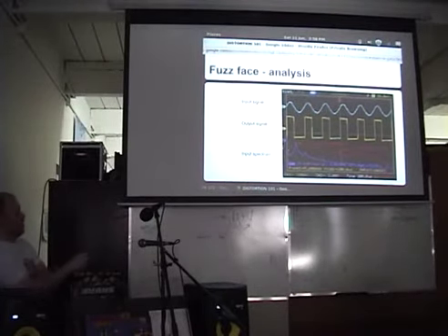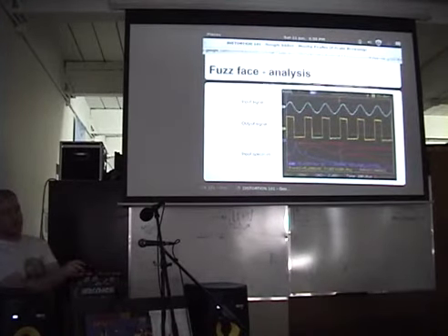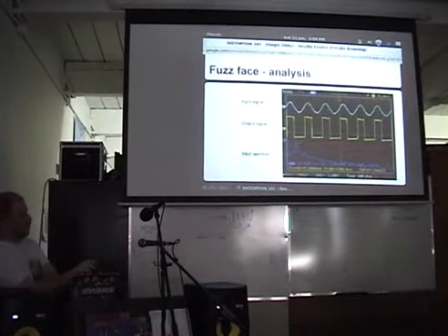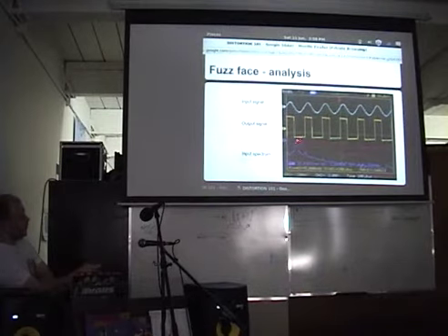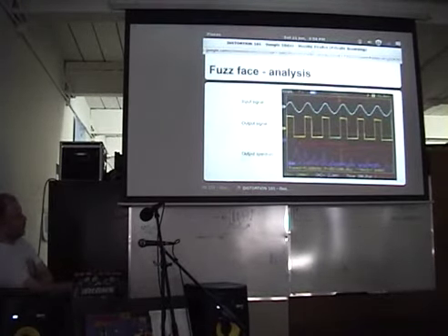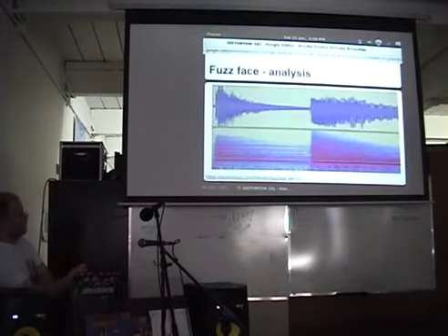So you can see here, this is the frequency plot of our input signal. If I didn't mention this before, by the way, values over here are the low frequencies and values over here are the high ones. So this is the frequency of our input sine wave. And as soon as we distort it, we get all these peaks at odd intervals of the input frequency that just sum up to make these really harsh corners again.